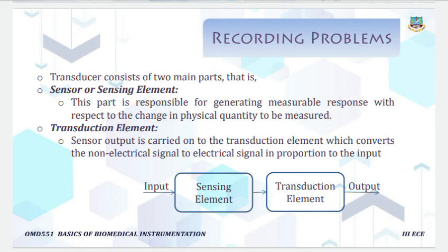Next, the transduction element. The sensor output is carried to the transduction element, which converts this non-electrical signal to an electrical signal in proportion to the input. So the sensing element takes the response, and the transduction element converts the non-electrical signal to the electrical signal.